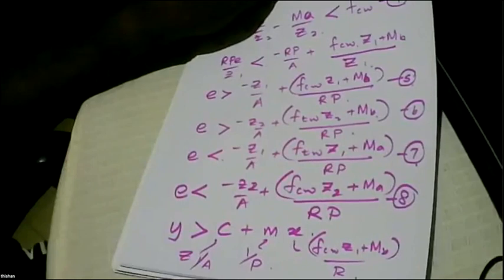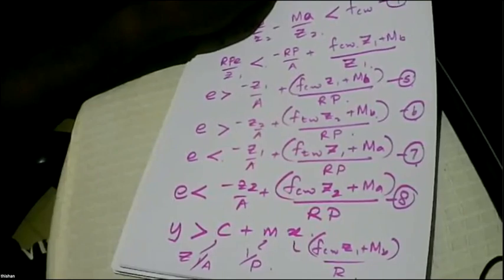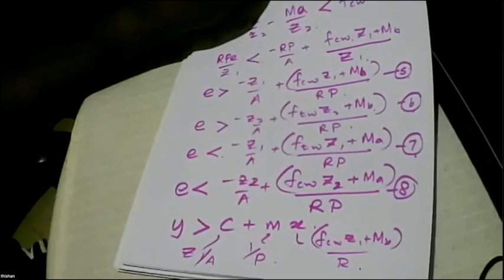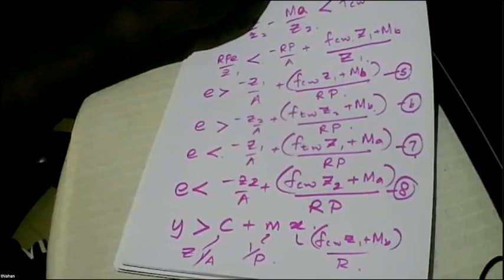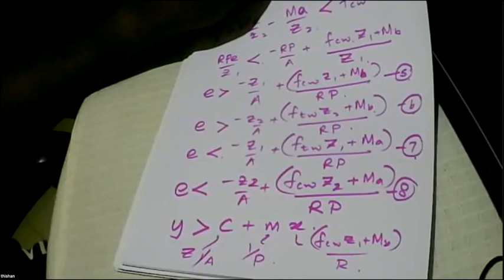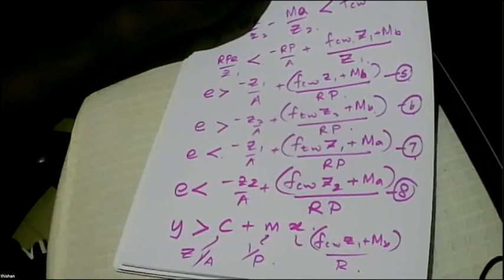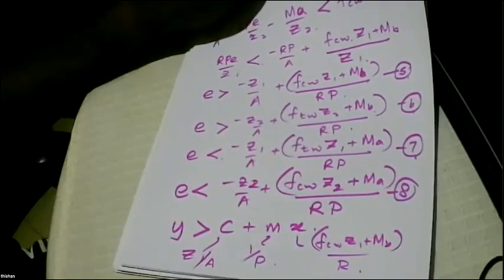Now you will find this beam, this continuous bridge design should be extremely simple. Why? Because the simple theory that we learned in the form of a graphical representation is applicable for continuous construction, and the equations are even simpler than what we got with the simply supported case. Because in the simply supported case, in one equation the pre-stressing force is P. In the other condition, that is under service, it's RP, after losses. But here, everything is RP.